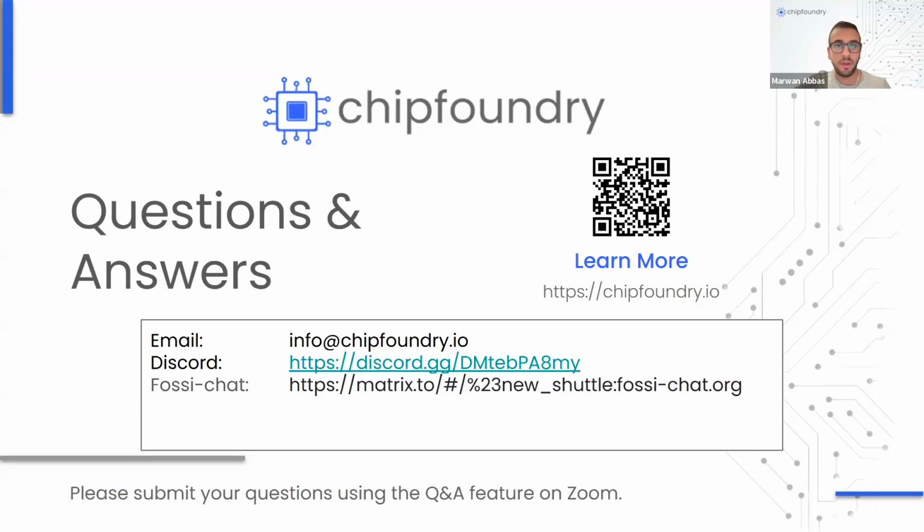Okay, there's another question. Based on the behavioral model, data are popped out when read is issued. Does this reflect on the same IP? When data are read from the IP, can it be read again? So it's a standard Wishbone protocol. You have to do a write operation and then you can do a read operation. So I would recommend to just pull our IP and experiment with it. It's a standard Wishbone protocol, even available with chip foundries, other macros.